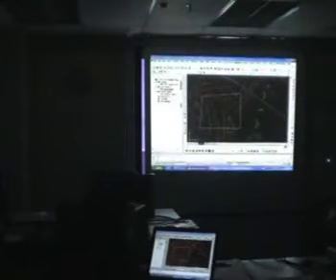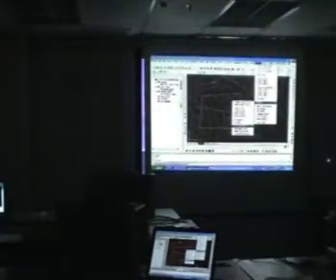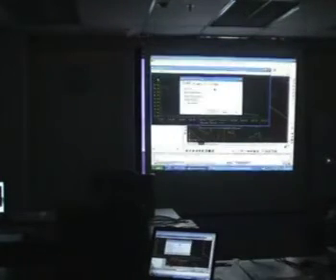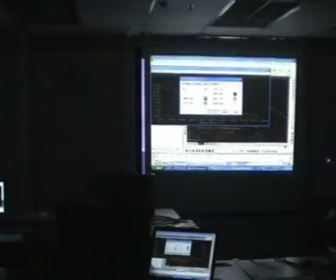In fact, if you want to check the sections, we'll use the quick section tool as just now. I'm just going to select this. You can see now you can see more than one profile. You can actually see up to a maximum of 8. See if I go to view properties, you can see up to 8 different surfaces in the same profile view.